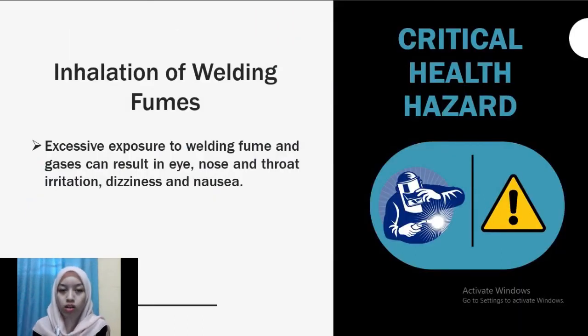Next, we found out that one of the critical health hazards is inhalation of welding fumes from the welding activity. This is because excessive exposure to welding fumes and gases can result in eye, nose and throat irritation, dizziness and nausea. Inhalation of welding fumes is considered a critical health hazard because welding fumes contain a variety of chemicals, and welding on stainless steel is the most hazardous welding activity.